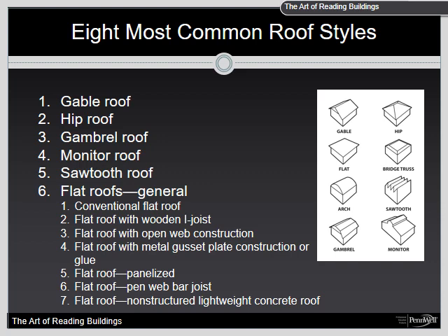It is important to note that newer roofs use 7/16 inch or 1/2 inch plywood or OSB as sheeting instead of the spaced sheeting. The OSB does burn faster, which leads to a faster fail time than the spaced sheeting and offers minimal resistance to fire.